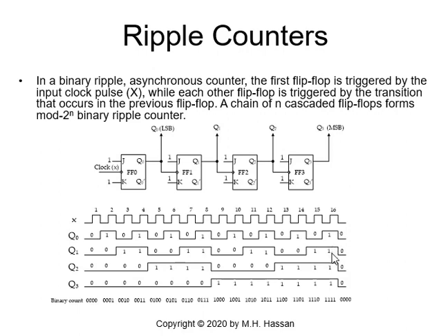So this shows you how simply the ripple counter works to generate all these frequencies. For instance, if the frequency here is 1000, you will get 500 here, then 250, then 125, and then half of 125, which is 62.5 cycles per second. So as you see, this is divide by n, and this is where the name divide by n came from, because of the change in the frequency: F divided by 2, F divided by 4, F divided by 8, and F divided by 16.